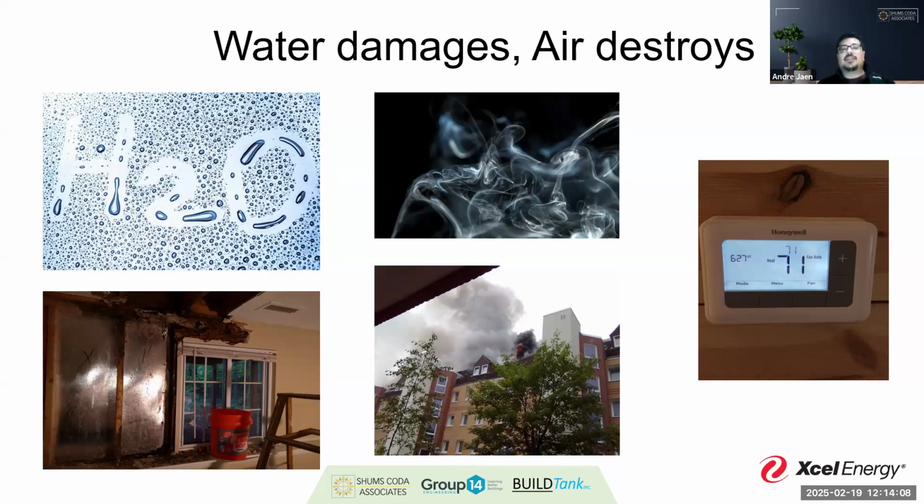Even before we're worried about the concept of retaining that heat and that energy efficiency with our insulation, we're really concerned about compartmentalizing that area for the fear of carbon monoxide poisoning, right? And then, of course, we have our thermostat there, and the reason we have that there is because the way that we heat our house and the way that we make sure that we mitigate some of our humidity is through our mechanical equipment as well. So we're using all of these things together as a system, like that EEBA slide that we had earlier kind of pointed to, that we're thinking about all of these things together.